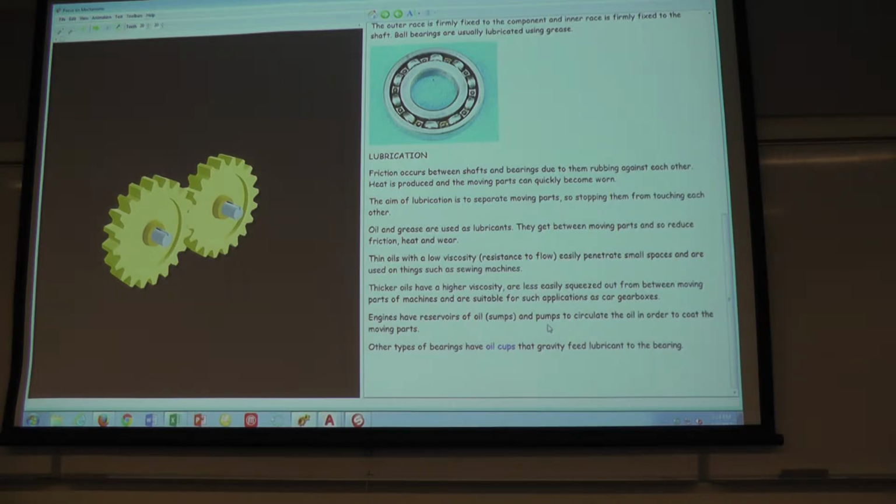All right, so it depends on your speed ratio. Remember speed ratio from our previous two projects? Taking the larger RPM number and dividing it by the smaller RPM number to get a speed ratio. In this instance here, there's 20 teeth and 20 teeth on the gear. We'll put a little rotating symbol on, and we'll put it in motion. They're going to spin at the same speed, and they're going to spin in opposite directions. That's a simple drivetrain of gears.